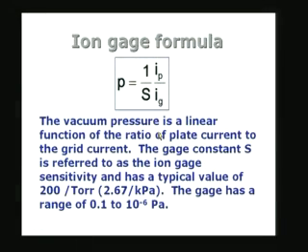So, there is an advantage of putting it inside the vacuum chamber, allowing it to hang inside there, and it is going to measure the pressure, and at the same time also provide illumination within the chamber itself. Usually the way we operate the ion gauge is, first you turn on the rotary vacuum pump, which will reduce the pressure to a sufficiently low value, so that we can turn on the high vacuum part, either the diffusion pump or any other pump which is going to be used for creating higher vacuum. That will be started only after the pressure has reduced sufficiently.